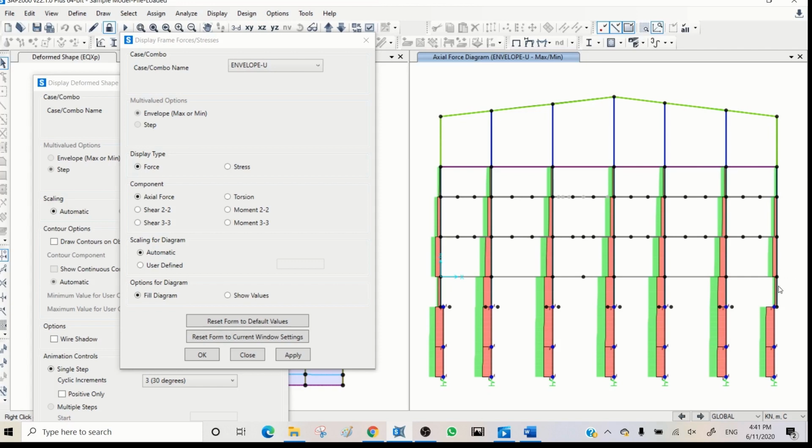Here is okay because you have a wall, and when the columns reach here, you have a shell element and load will be distributed. So it's logical for me. I don't have any issue with that, because actually the retaining wall is participating to take load of this column, which is pretty normal. You have a deep beam here between piles, and that deep beam can help you to transfer load. But you need to ensure that what you have is correct before moving on for design.